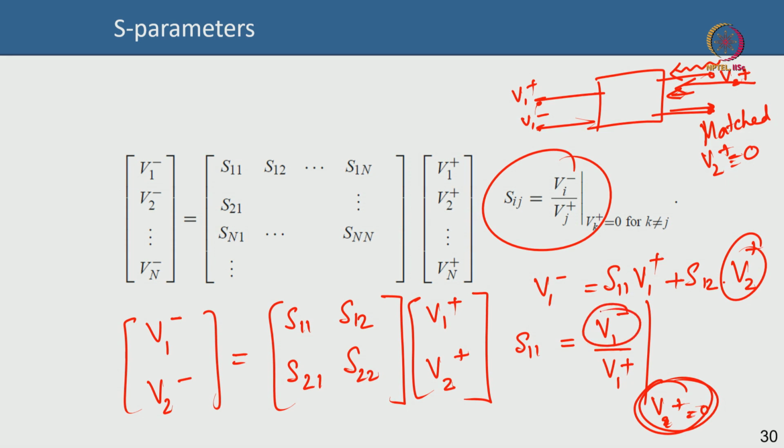and the ratio of the reflected wave on the input side to the incident wave on the input side, which you can measure very well, how much you are sending in and how much you are getting reflected back, you can measure in the VNA. That ratio will give you S11, and this is for a certain frequency, and as you change the frequency you will get S11 across a range of frequencies. Similarly, you can find S21, S22, S12, etc.